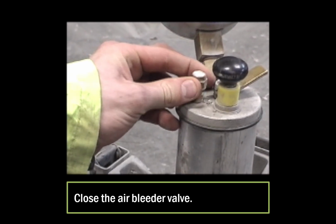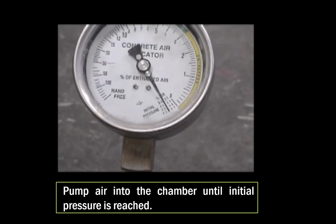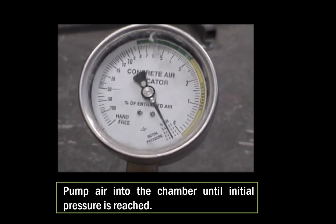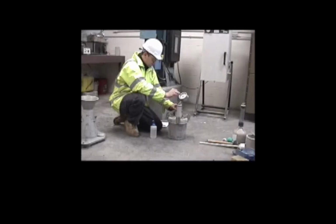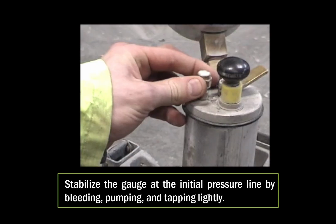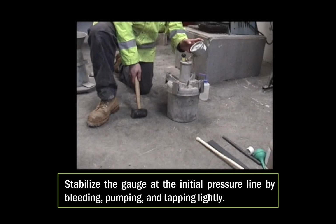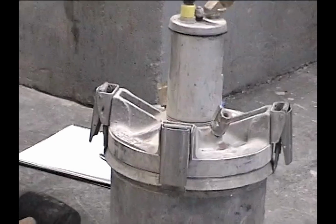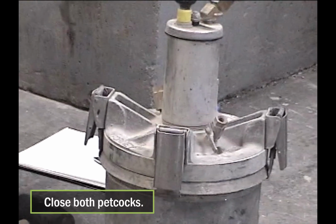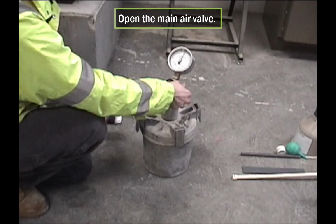Close the air bleeder valve on the air chamber and pump air into the air chamber until the gauge hand is on the initial pressure line. Allow a few seconds for the compressed air to cool to normal temperature. Stabilize the gauge hand at the initial pressure line by pumping or bleeding off air as necessary, tapping the gauge lightly by hand. Close both petcocks. Open the main air valve between the air chamber and the measuring bowl.